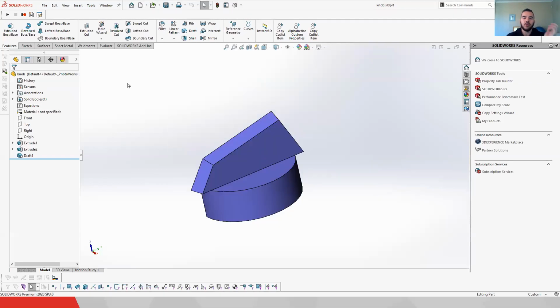One of the main questions that I always had while I was still in university is that sometimes I can't see my surfacing tab, or my weldments tab is maybe missing. It can happen that during the installation, certain tabs are actually selected by default. It depends on the settings that you're currently running. If you had an old installation of SolidWorks, it will actually keep some of the information, and some of it might be broken. Some of the links might be broken.